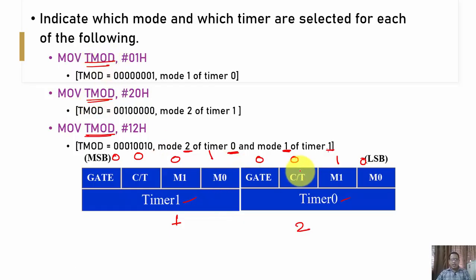So in this way, by configuring this TMOD register, we deal with the timer operation. If you see everywhere, in all these instructions, this bit, here also this bit, and here this bit and this bit, these bits are nothing but C/T bar, and they are made equal to 0. Means in all these examples, whatever 16-bit timer is available is operating in timer mode. So this is the way in which we select the proper timer in the specified mode of operation.